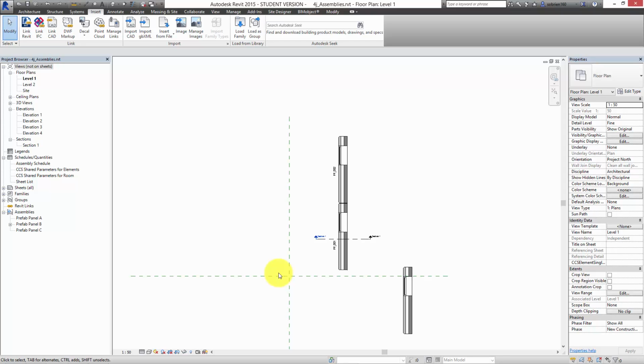Any questions? Yeah. So if we, for example, make a component drawing, it should only be one element. Yeah. Even though there is a lot of elements. It depends on the process. Like if you're getting precast concrete elements made, and then you're going to hang some bricks on them, for example, but that's coming afterwards with the bricklayer, then you would only make the component of the concrete element, because that's the bit that you want to get made. Yeah. In this case here, I'm assuming we're going to get the whole panel with insulation and everything made in a factory. But you really have to think about what's the procurement method first of all.